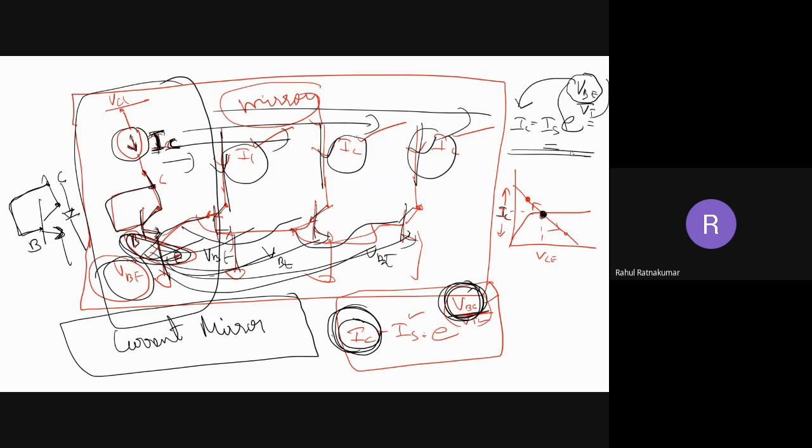And what is an oscillator? An oscillator uses feedback. Using the concept of feedback, we use the Barkhausen criteria: the magnitude of AB equals 1, and the angle of AB equals 0 degrees, so the phase is 0 degrees. Then I'll get feedback and a sustained oscillation. That is called an oscillator. The different kinds are LC, RC, and crystal oscillators, and digitally we can also make square pulses using a 555 timer IC. Those are the applications part. And different types of modeling, small signal modeling and large signal modeling, and different types of transistors: BJT, MOSFET, JFET, and Opamp applications, Opamp properties and characteristics, and diode properties and characteristics, ideal diode, non-ideal diode, all those things.